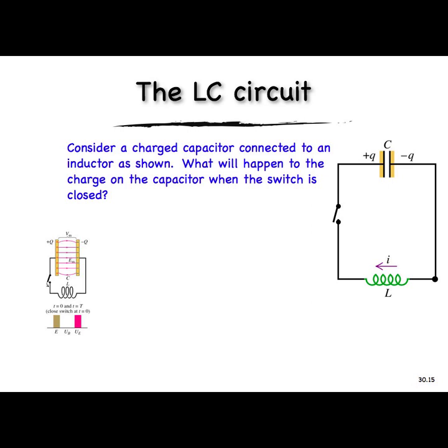So I close that switch. That causes the current to want to go to 0. That very rapid change in current produces an EMF that continues to drive current through the circuit. So even after I've closed the switch, current keeps flowing through the circuit. The inductor acts like it gives inertia to the current. Current can no longer stop instantaneously or change instantaneously. It takes time to do so.